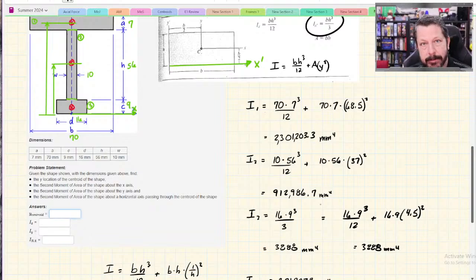So you get the exact same number. If you're unsure if you can use the x prime, then don't use it. Use the centroid version and apply the parallel axis theorem. The rule with the x prime, the one that doesn't go through the centroid, is that you cannot apply the parallel axis theorem to that equation. It has to already land on your reference axis.